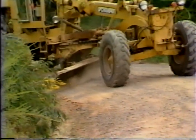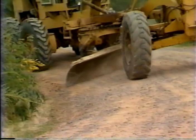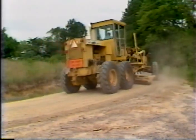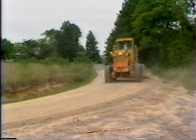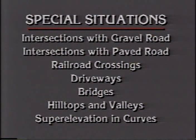Transition from the normal crown to superelevation, 50 to 100 feet back from the beginning of the curve. Transition from the superelevation back to the normal crown, 50 to 100 feet beyond the end of the curve. It is important that all of these special conditions be handled properly in the maintenance of gravel roads.